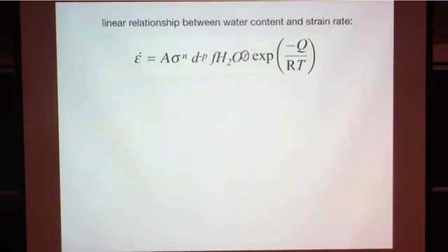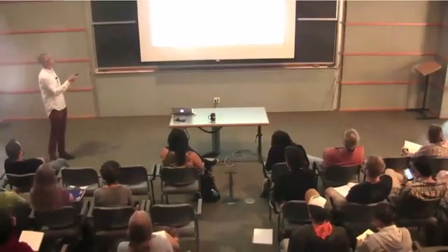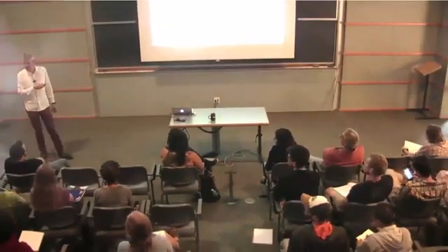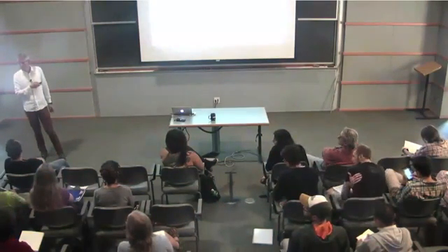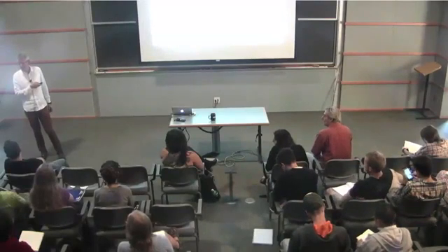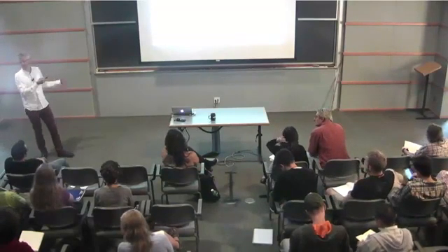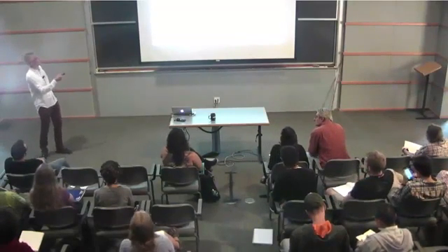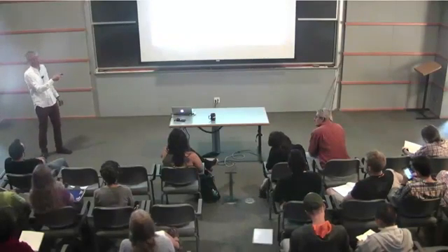This is a general equation. For dislocation creep, this would be 0. Because you don't know the diffusion regime, you assume that you can have all the previous regimes of deformation. So this is a general equation where you just vary the parameters. For diffusion creep, n would be 1, p would be 3. For dislocation creep, n would be 3.5, and p would be 0.